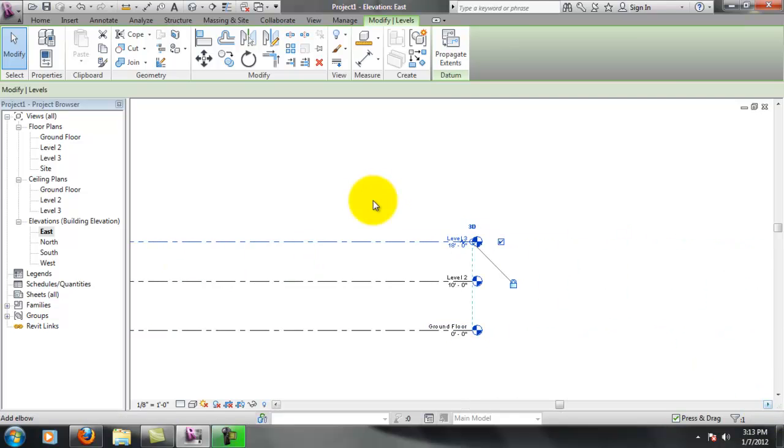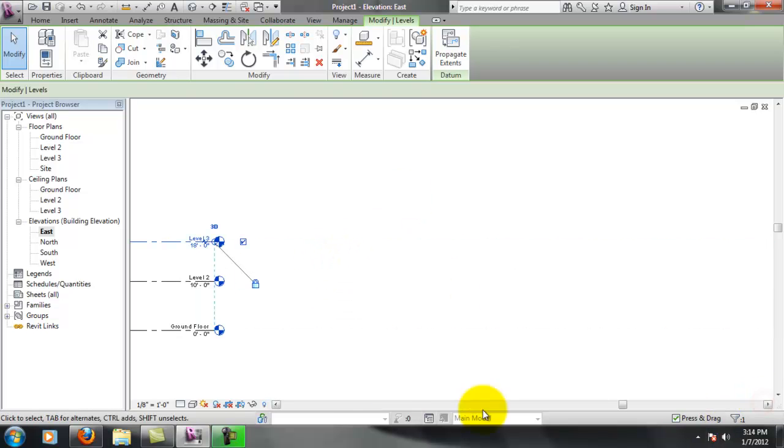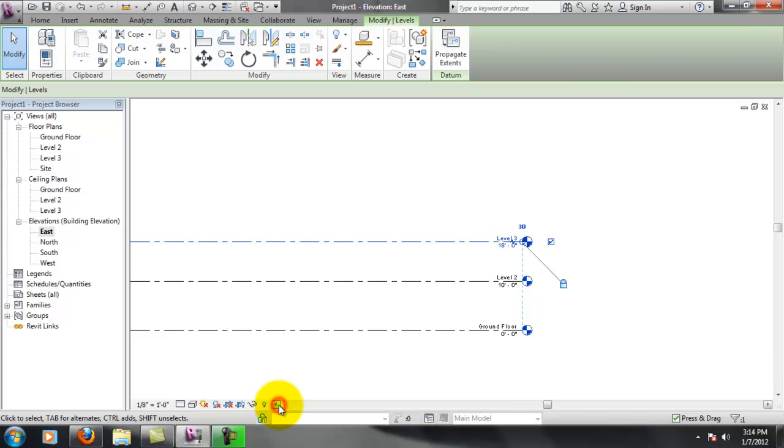You'll also notice when you click on these components that you get a measurement that pops up. Whenever you see a measurement like this in Revit that's blue that automatically pops up, this represents a temporary dimension. This is how you enter heights and widths. This is how you tell the difference between where you want things to be placed.